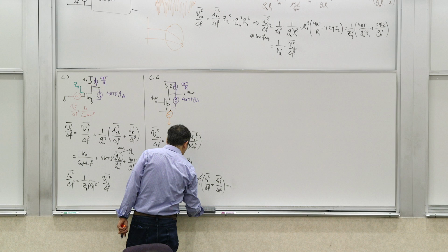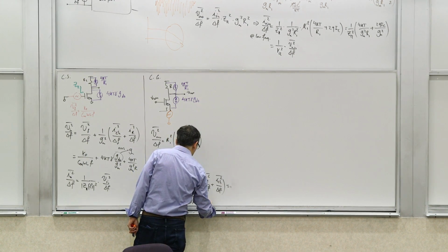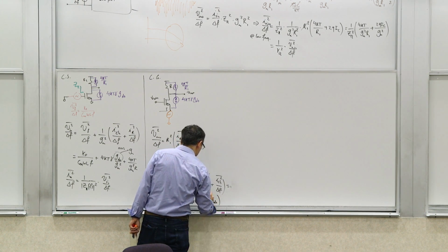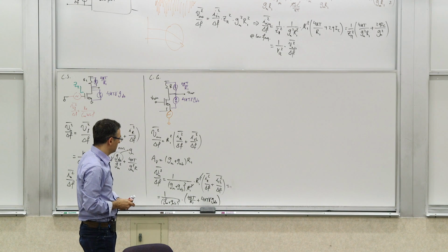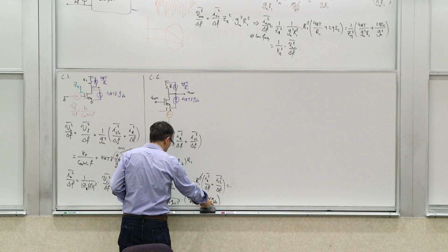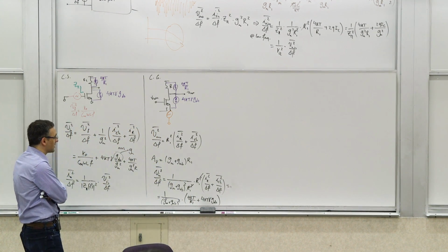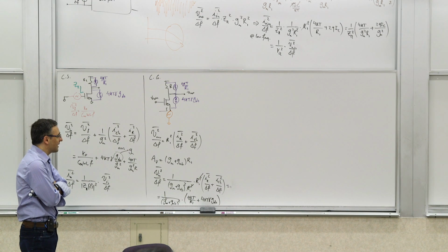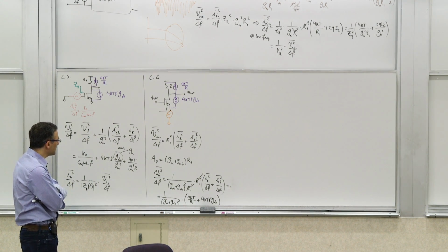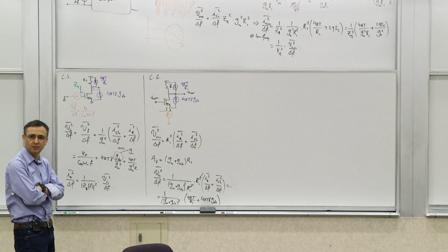You get 4kT over R1, and then you get 4kT gamma GD0. If it was a non-velocity saturated device, GD0 would be gm, so this would be close to 1, not exactly 1, and the other one is whatever it is. Depending on the relative size of gm, one of them can dominate. So that's the input referred voltage noise.